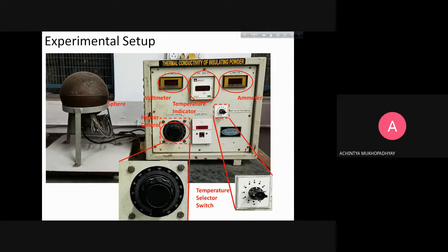Actually, there is some support, so that way it disturbs the spherical symmetry to some extent. For example, even here you can see that you have to have this ring like support to hold it. So strictly speaking, this also provides a heat transfer path. So that way there is a disturbance.